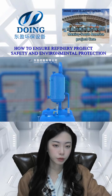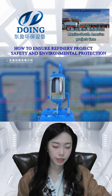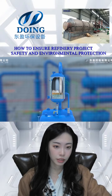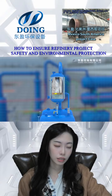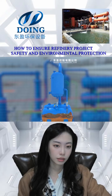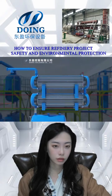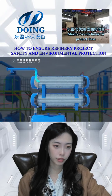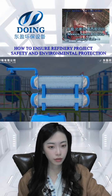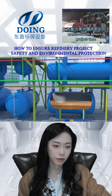The batch type, like the fully continuous one, has the feeding system, pyrolysis system, condensation system, discharging system, and the purification system. They just have different devices, different techniques, and different efficiency. Like, we need to cool down the carbon black before discharging it. But if you use the continuous one, you don't need that. We can discharge at a high temperature. This is the main difference.